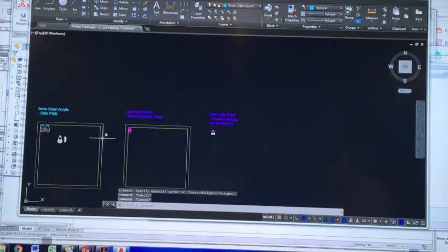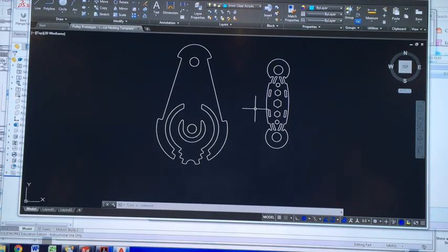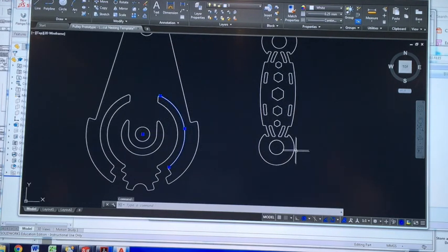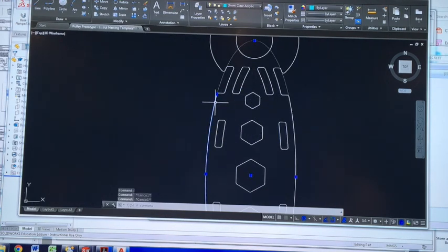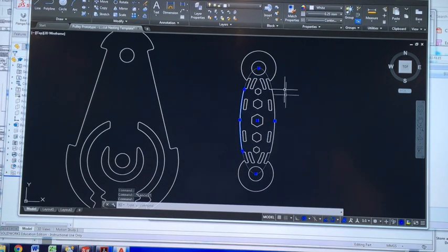I'll show you a little bit more with these two parts here because I'll separate their layers as well. These ones are a little bit different because I've got some different shapes. You can see on this one here as well, when I select this part of the ellipse, that I've got these other command control points around here. Typically that's indicating a spline, which is something I don't want. Hopefully when we convert that to a polyline, that will remove any issues there.